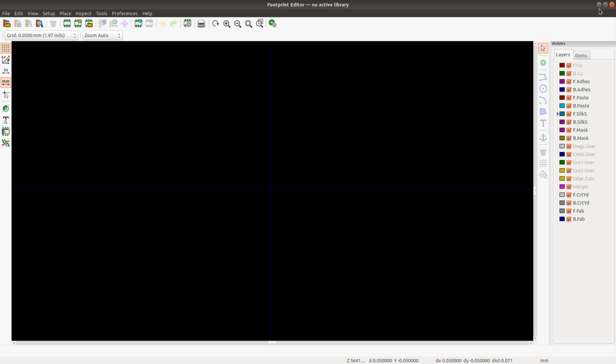I don't want to have those footprints in the KiCad default library, for the same reason that I don't want the schematic symbols in their default libraries, because I could update the default library someday, and I don't want to have to do a new review of the components just to make sure nothing has changed. So I'm going to copy this RJ45 into my custom library instead.